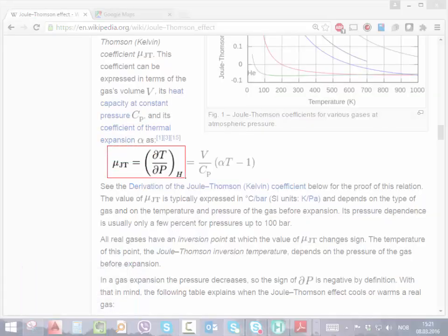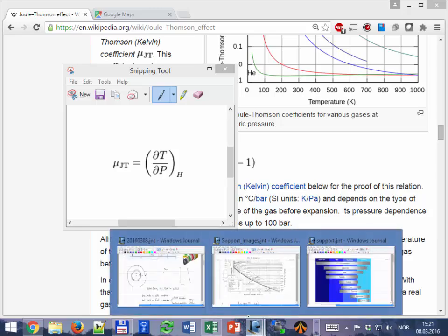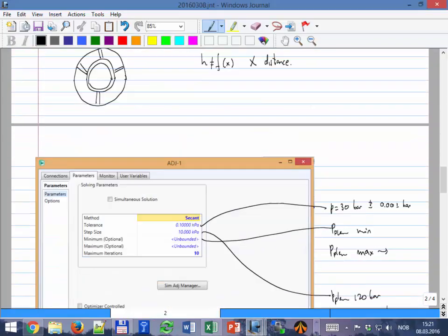So that's a Joule-Thomson coefficient. It's a coefficient that tells you the variation of temperature with pressure. And usually if you are formal and you do the derivation of the equations of flow of gas, assuming energy and also momentum equation, you will get that coefficient that comes out in some place in the equation. And it's very important especially for gas.